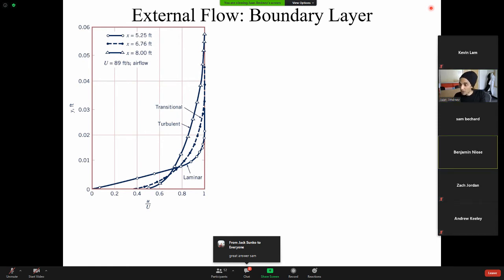Yeah, absolutely. So you look at the velocity gradient, and we know that our shear stress is going to be a function of that velocity gradient. So then the larger the velocity gradient, the higher the wall shear stress. So that's why everything goes back to what we were talking about a few minutes ago, that if you have a flat plate, you care more about that frictional wall shear stress, because you have your boundary layer. It's essentially what's going to contribute the most amount of drag.